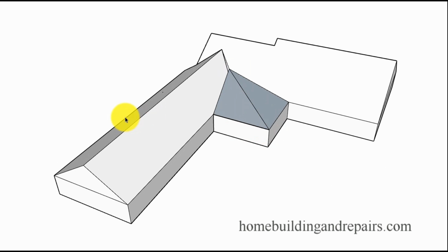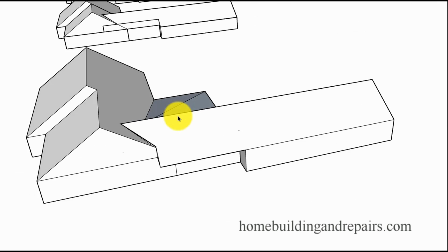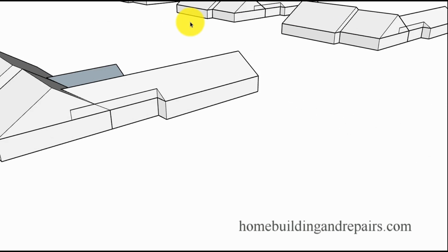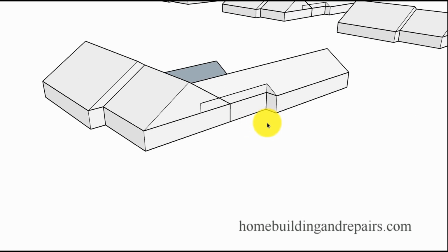This one here, this section goes to the side, kind of creates a porch. So if you wanted to, you could put a post here with a beam and then have a porch coming through here. And again, this doesn't have to be like this, but it gives you an idea if you're going to have a long gable. You could always die this back up into here with a hip. I say that, but I would have to draw that out to verify that.